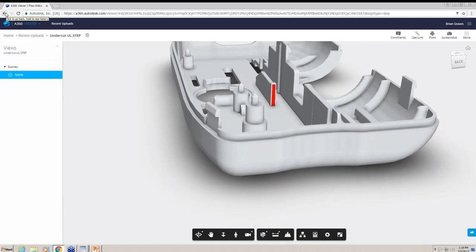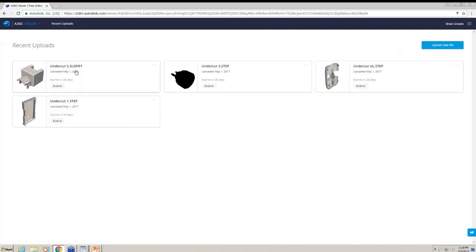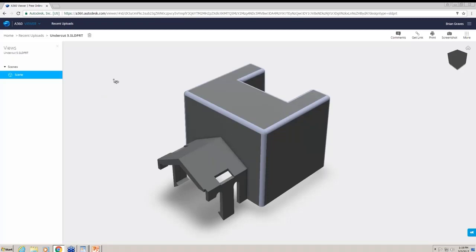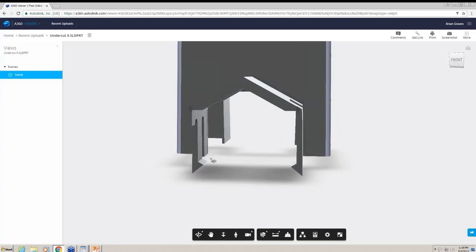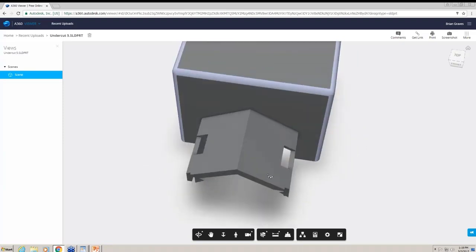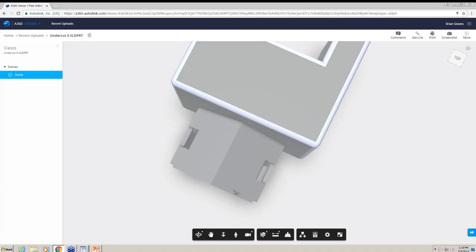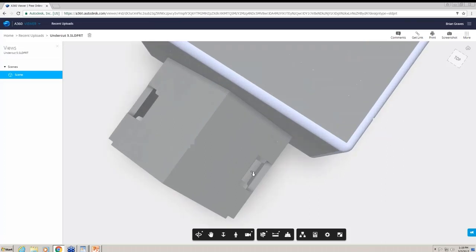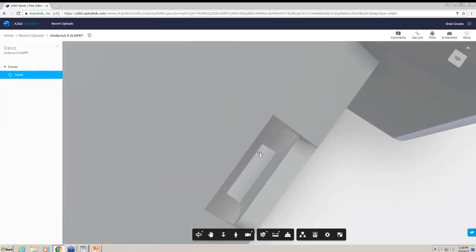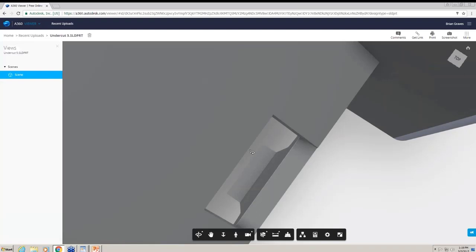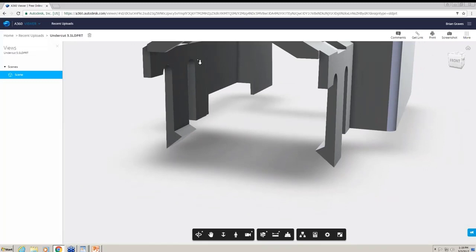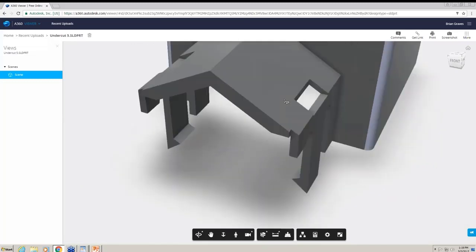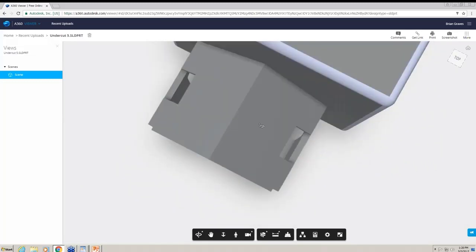Now, for the same feature, I want us to go back and take a look at a different design. The person who designed this part took a different approach. They have the same type of clip features, however, what they did is what we call window out. They put a little window into this feature coming down from the cavity or core, and it's going to come all the way down to hit the top surface of that clip. So instead of having to have an internal hand load to create this clip, they changed it and made it into an open and closed part.